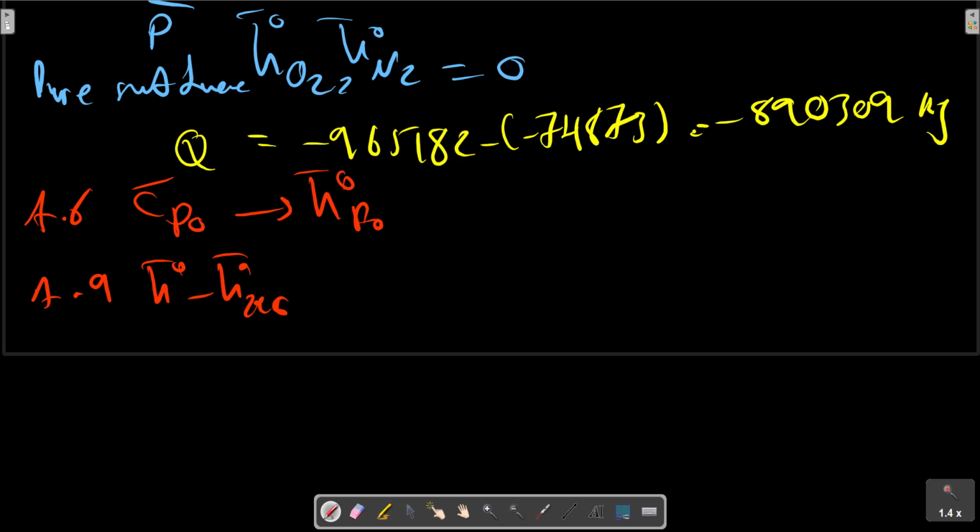If a table of thermodynamic properties is available, delta h bar can be found directly from these tables if a real substance behavior reference state is being used, such as that described above for liquid water. If a hypothetical ideal gas reference state is being used, then it is necessary to account for the real substance correction to properties at that state to gain entry to the tables.